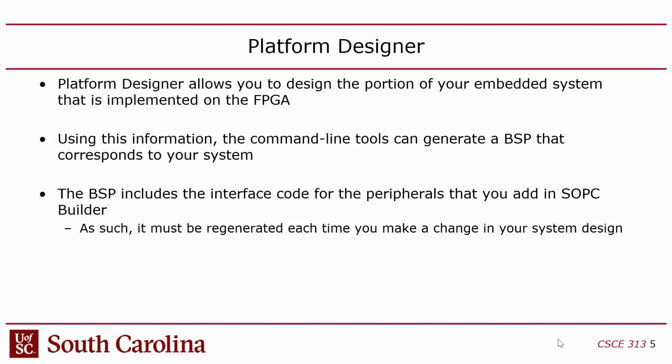However, bare metal code is a little bit of a misnomer because in reality, you still have a very thin layer of software that you can use to help. It's not just your code and your code only. There's a layer of code called the hardware abstraction layer. And it's not an operating system per se, but it fills some of the duties of an operating system. It provides some drivers for you, basically, that we can use. Okay? All right, so that's the BSP.